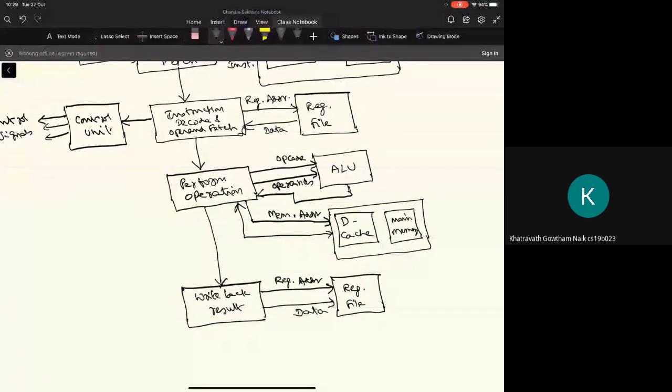It's correct. As we have seen, for an integer add operation, if it's an n-bit operation and a ripple carry adder, it takes 2n tau. If it is a carry lookahead adder, then it takes a different amount of time. And if I use a carry lookahead adder with the higher propagate and generate terms, it takes a different time. So it all depends on which circuit is used.